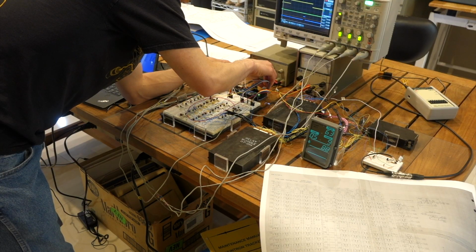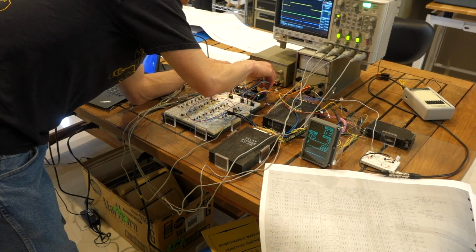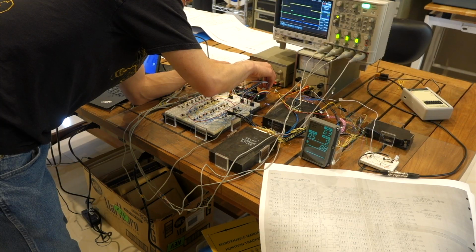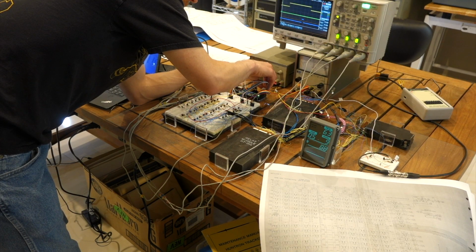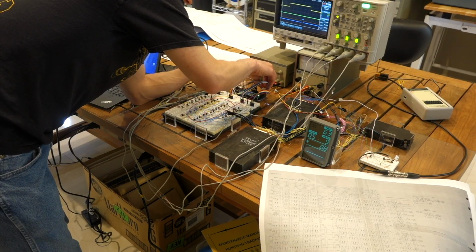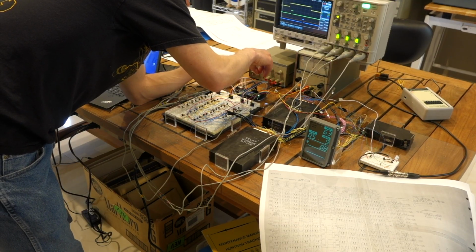We had a digit wiggle for a second. So the signal's coming out here, it's just not making it through the wires. So I'm probing at the Arduino end, and I'm seeing that row drive signal at this end of the wire, but not at the other end of the wire. Because your wire is non-conductive. It is not being a wire. I bet you it was a crimp on the end there. I think you might be right.